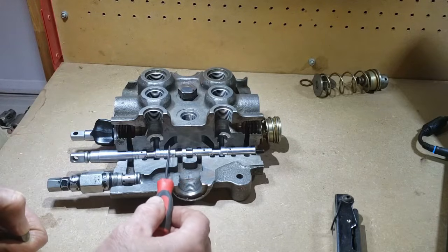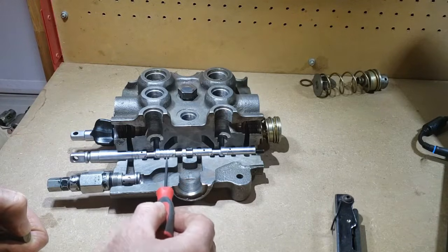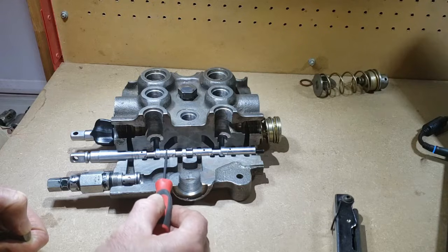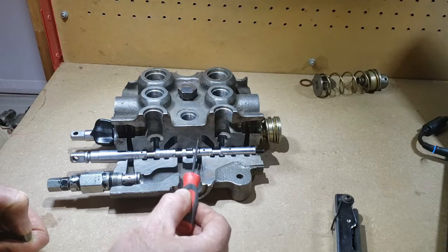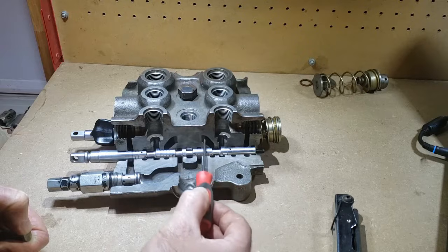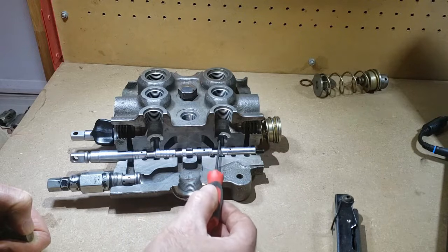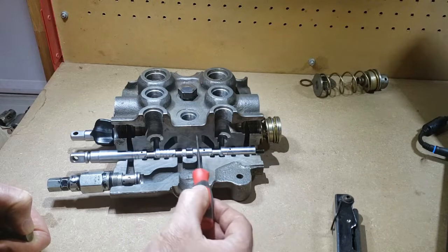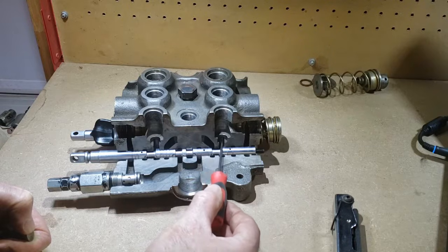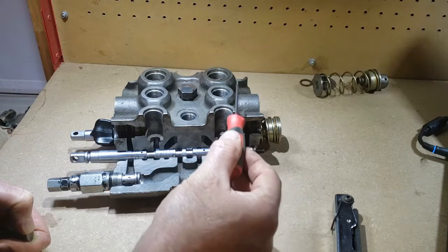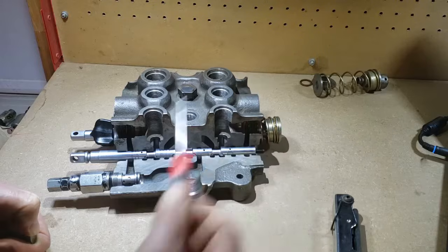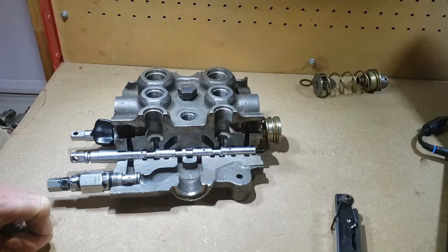And when it comes down to this side of the spool, it's still blocked here. The spool land is blocking it, so I can't do anything there. But now, because the spool's moved over to the left, this notch right here is open. So oil can begin to flow in around this notch and out to this work port, which is going to tee off and go to the head end of both of the loader lift cylinders. So we got two loader lift cylinders going to be lifting in parallel.